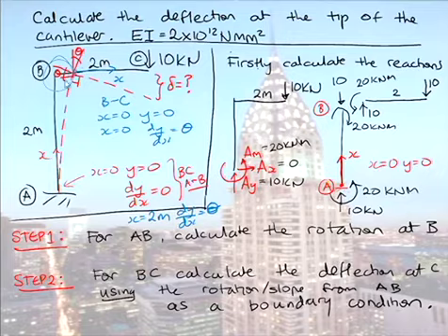and also as a result of this corner rotating. So when we do this problem, we actually will split it up into two parts, AB and BC, which is what I've done here. And when I've split it at the cut, I've had to, of course, draw all my internal forces in there. So I went through equilibrium and worked these out. And I said the steps we will go through to calculate this vertical deflection is, firstly, we look at AB. For AB, we'll calculate the rotation at B, because it's only this rotation theta that we are interested in.